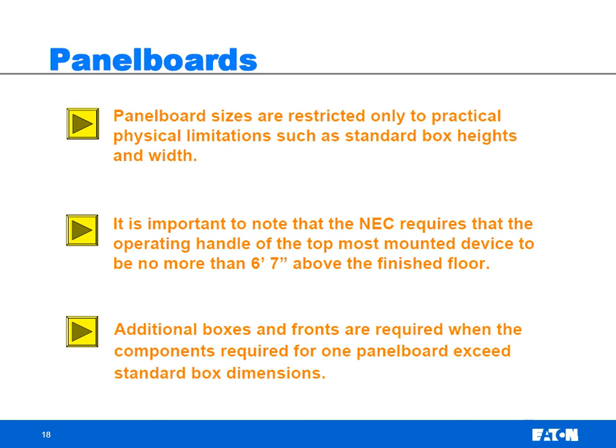So whether it's the main breaker at the top or a main breaker at the bottom and the feeder breakers at the top, 6 foot 7 is the highest handle that it can be. Now, I don't know if you're a 5'1" electrician, if that's going to do you any good, but the theory is you need to be able to shut that off at the top.